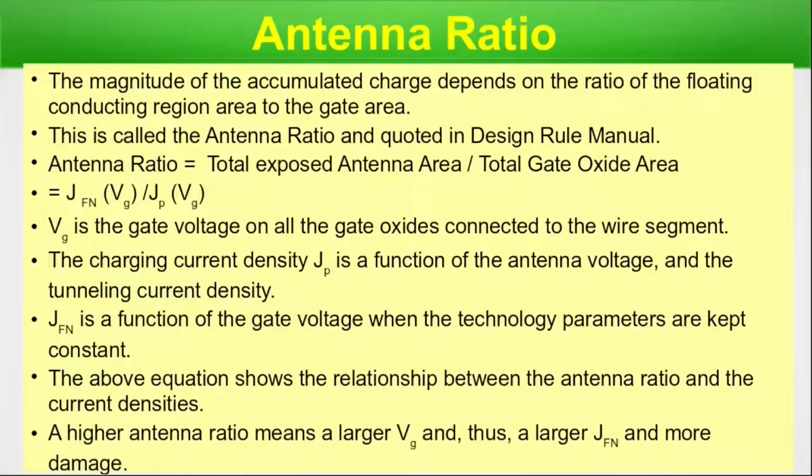A higher antenna ratio means a larger V_G, thus a larger J_FN and more damage. This ratio is very important with respect to the physics happening behind the antenna breakdown. So we're done with this particular slide. Let's move on to the next slide.